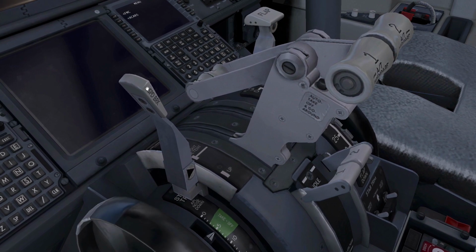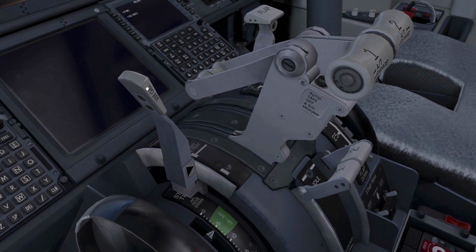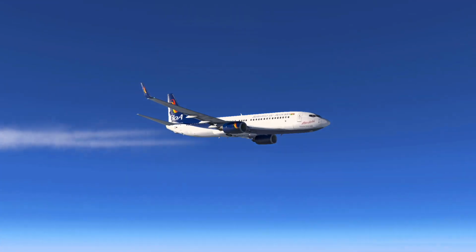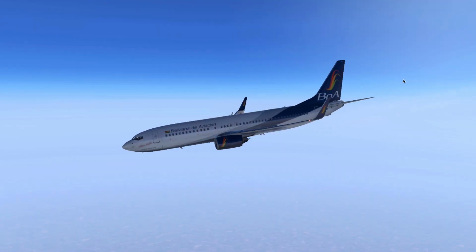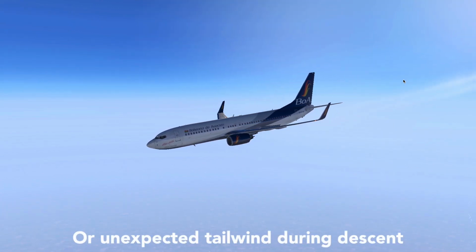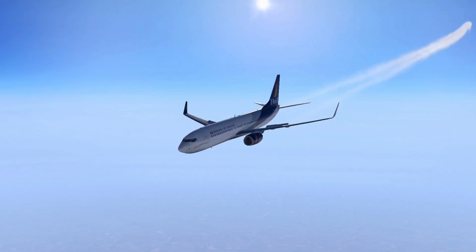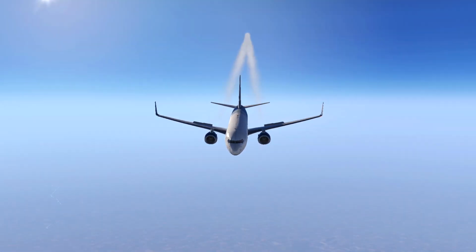Controlling aircraft energy involves balancing airspeed, thrust and drag, and the flight path. In this tutorial we're going to get high on the descent profile, and this can be due to several reasons, but the most common ones are due to ATC restrictions. That means that the ATC sometimes does not clear you for descent, and this is usually due to traffic crossing below your flight path. Another reason can be a poor descent plan. Either way, the crew action should be the same. Try to recover the descent profile in a safe way, so the aircraft can be in a totally stabilized profile once at 1000 feet AGL.